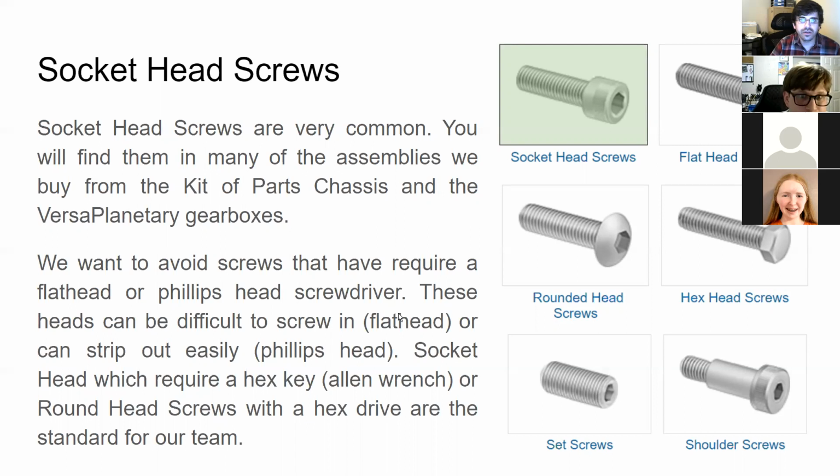And because the socket head is bigger, we tend to prefer using the round head screws. So we stock a lot more of the round head screws than socket head screws, but not for any significant reason other than socket heads tend to be a little bit larger, which doesn't package as well when you have limited space.